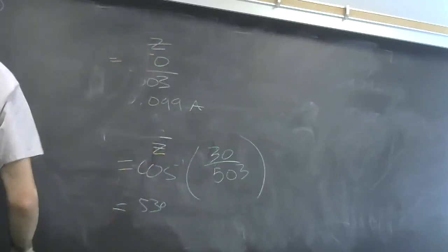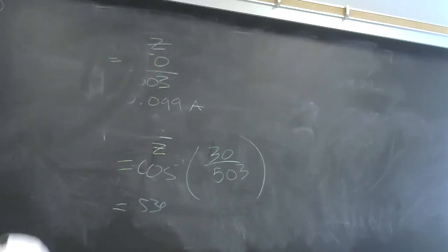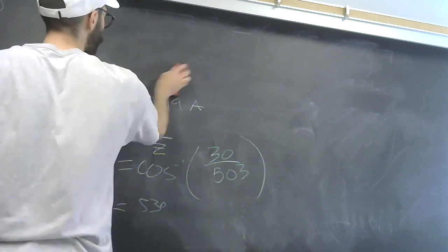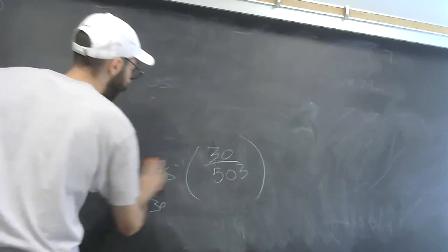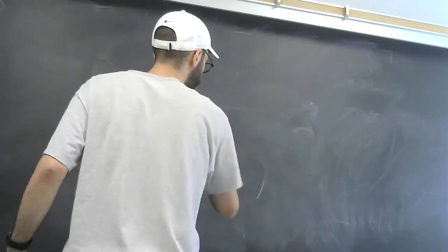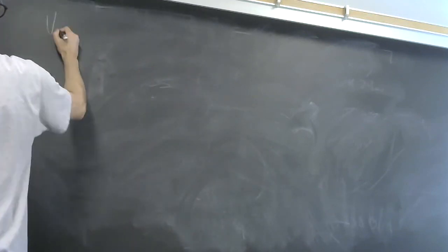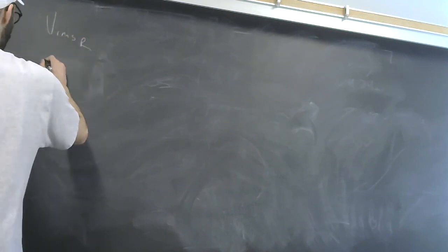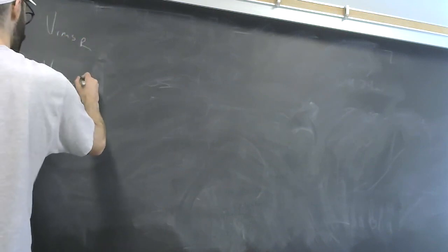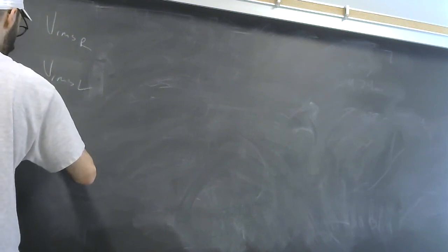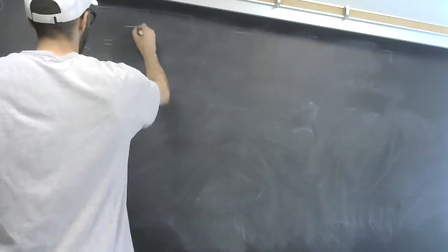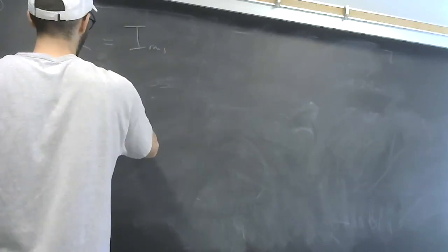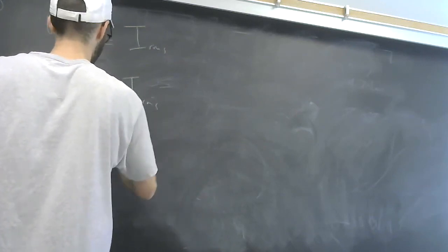we're finding the voltage, what do they have it called here? The RMS values across each circuit element, right? So there's going to be one across the resistor, the inductor, and the capacitor. And their equations are essentially very similar here. I'm going to say V RMS resistor, V RMS inductor, V RMS capacitor. Okay. So every one of their expressions has that IRMS value.